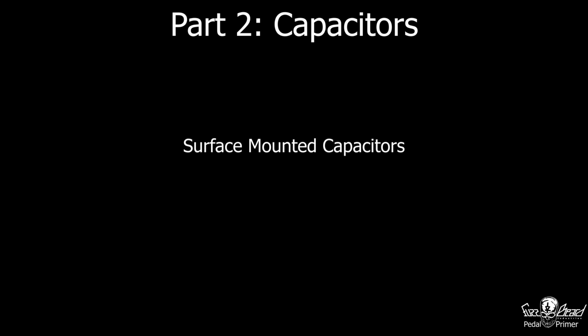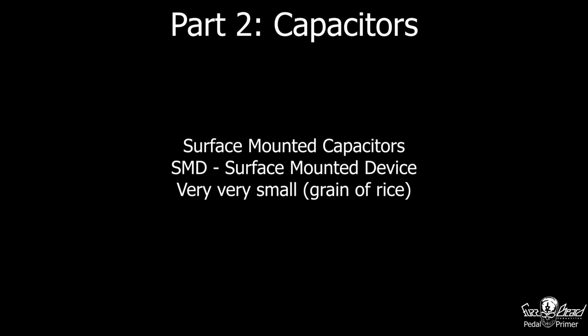This is something of a bonus item for this list, as it's not really a type of capacitor, more of a class of component in itself, as you get all manner of surface mount components from resistors, capacitors, op amps, diodes, all that sort of stuff. But surface mount, or SMD, surface mounted devices, these components are typically much smaller than their through-hole counterparts, and often used where small board sizes are required, allowing a much more densely populated board that would be impossible to achieve with through-hole parts.